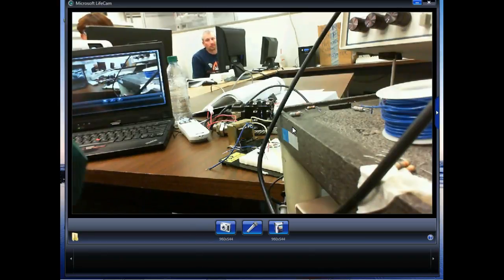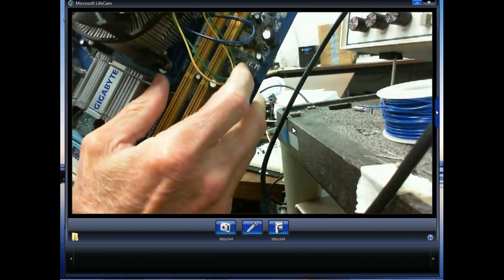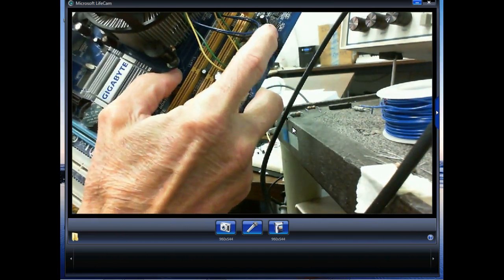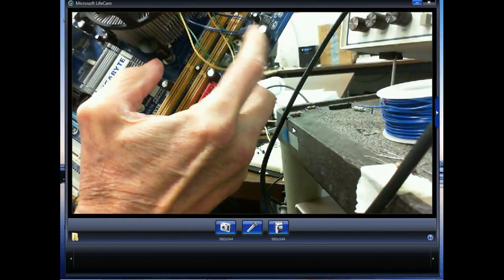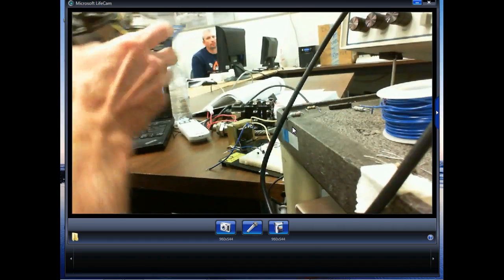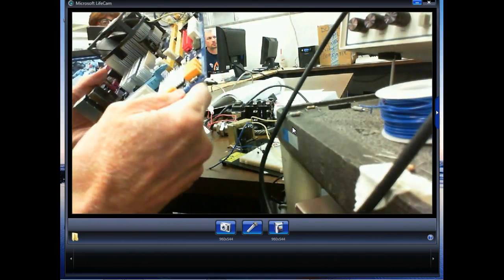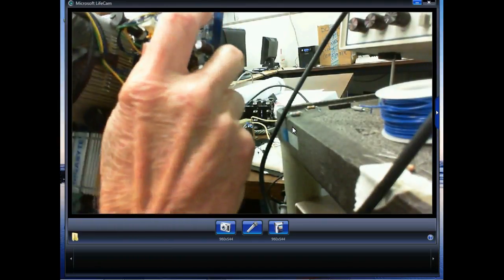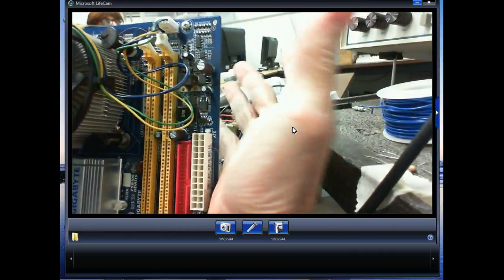By the way, this guy here, it's bad, so y'all don't have to worry about hurting it with static electricity. Yeah, the power supply blew out on it. First we had a cap that blew up, and we replaced it, and it worked for a little while, then it blew again, and the whole power supply section burned out in it. But you can look at all these little 3-lead devices, especially up here in this corner right here, and these are all 3-lead surface mount transistors.